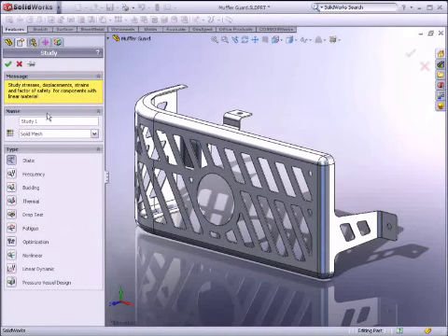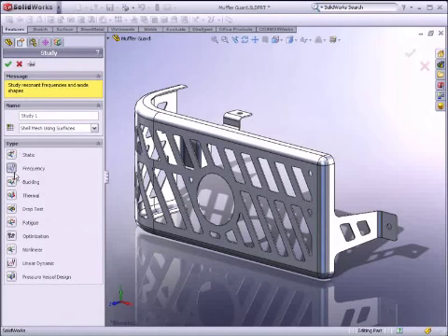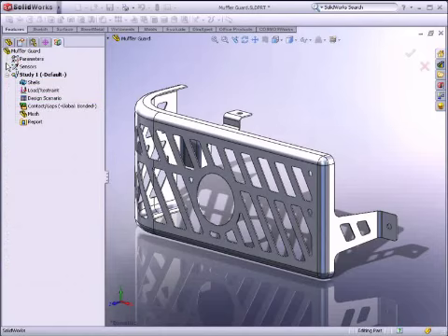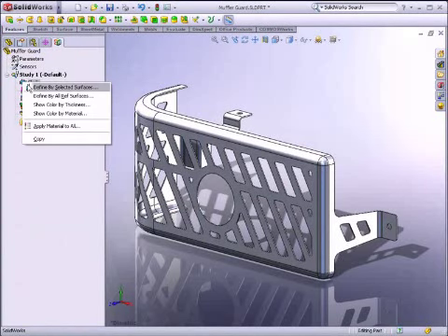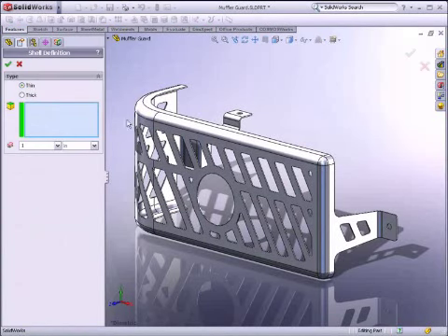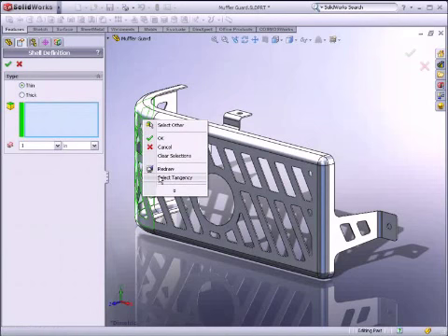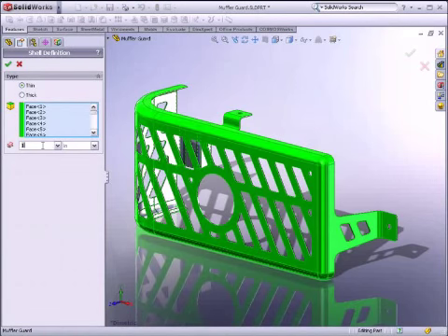First, let's simulate the thickness of the part with the shell in SolidWorks Simulation. Since the model doesn't have to change, only the thickness entered in the shell will change. We'll save time on meshing and on changes. The material set in our SolidWorks model is used by default, which we will use here.